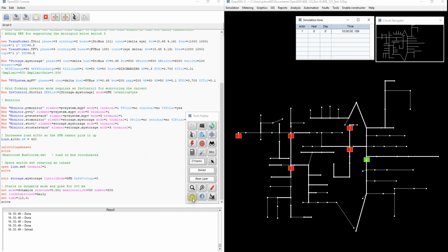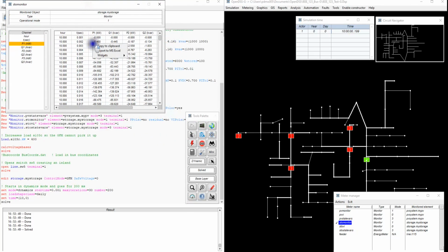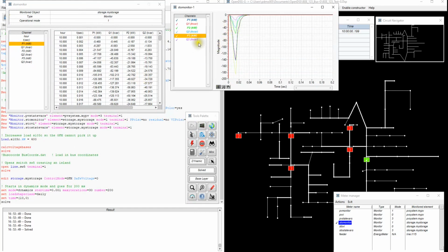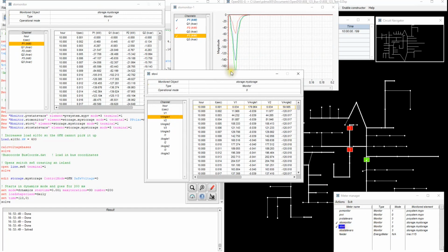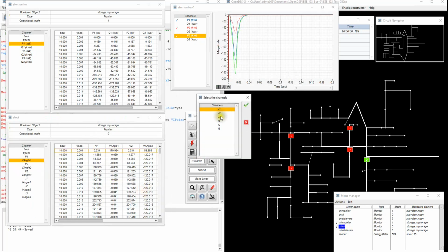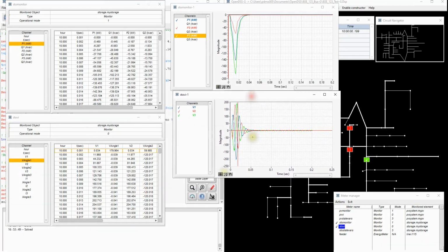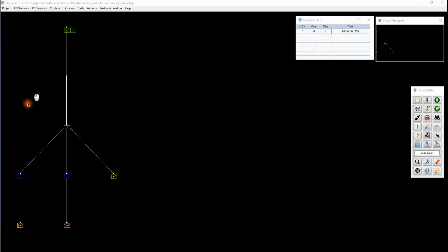So after the simulation runs, I'm gonna open the power monitor that we had for the storage, and I'm gonna represent the power as a QSTS. Here we can see that the active power was initially delivered, but then when the storage device realizes that it cannot pick up that load, it basically cancels the black start and starts turning off. From the waveform point of view, in terms of voltages, we can see the analog representation of the vectors informing us on how the black start was canceled, given that the storage device was not able to catch up with the load within the microgrid.